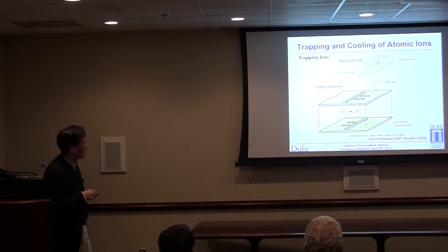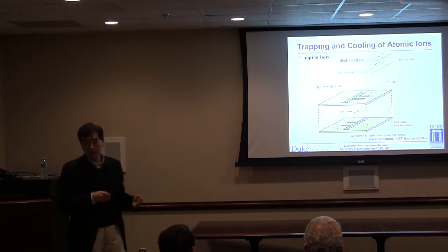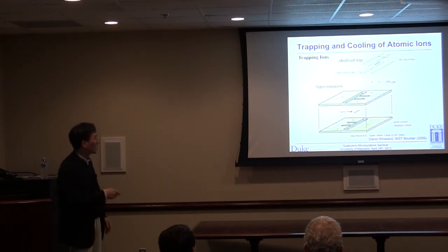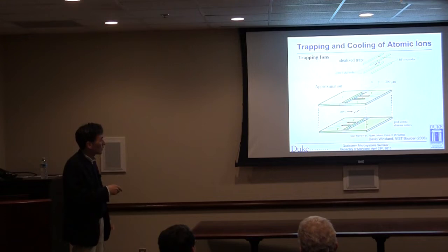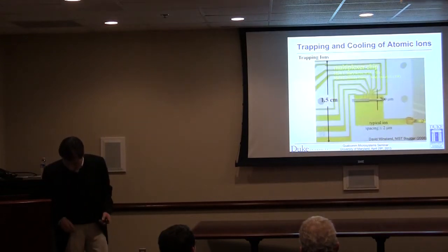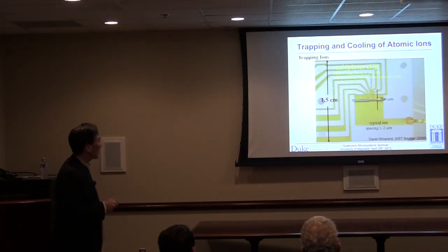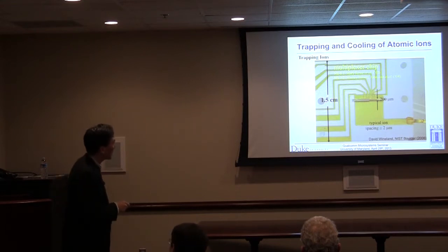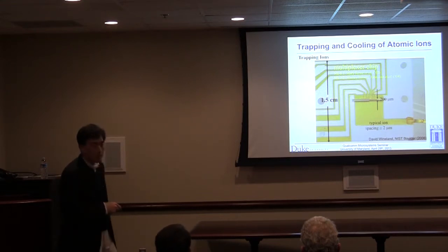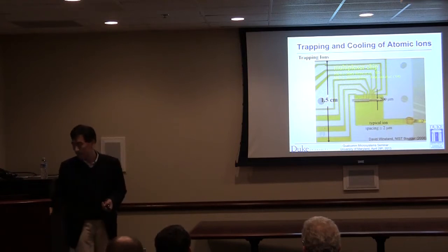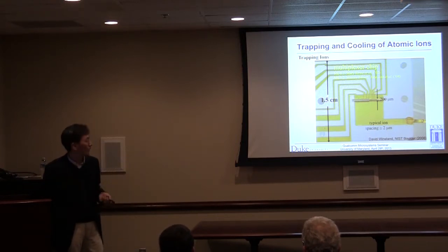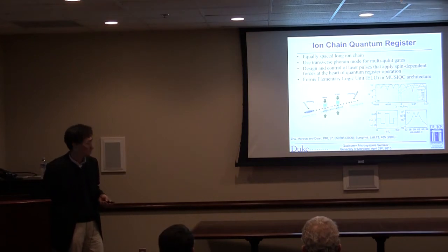And then you can actually use this 1 and 1 prime here as RF electrodes, and these 2, 3, and 4, and 2 prime, 3 prime, and 4 prime as the RF ground and DC electrodes to map this structure onto something that is a little bit more manufacturable. But these devices are still hand-assembled, and they can make multi-segment traps this way. But by the time you want to go to very large numbers of segments, then you really can't do it this way. We have to really go to microfabrication techniques.